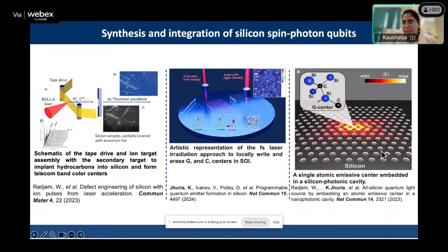And also other recent work that we did was embedding these color centers into various platforms. So PIN being the electronic platform, which I already mentioned. Here what we have done is also embedded it into photonic cavity, and also waveguides more recently. What that helps when you put this kind of color center in a photonic cavity is you can enhance the emission rate, which at some point in the beginning I mentioned is also critical, so that we get more photons per second to have better sensitivity.